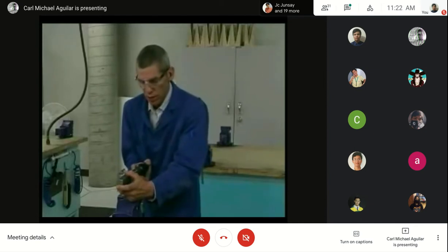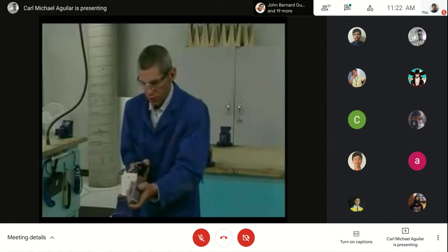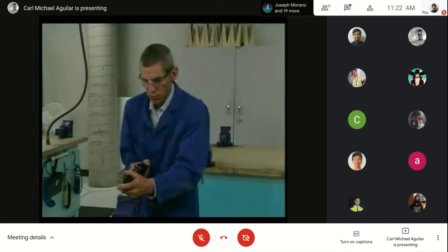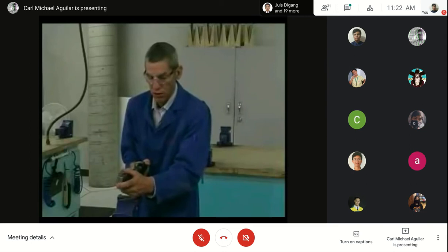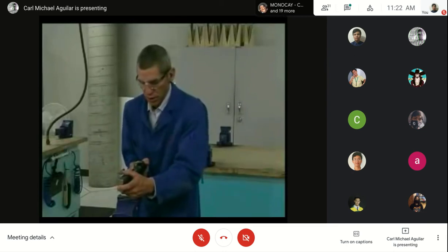So we're going to go ahead and do the riveting process. I'm just going to check that I'm perpendicular, that my bar is onto the rivet and nice and perpendicular, and then I'm using my fingers onto the coupon or onto the aircraft structure to support the bar so it doesn't go sliding away. Ready? Go.